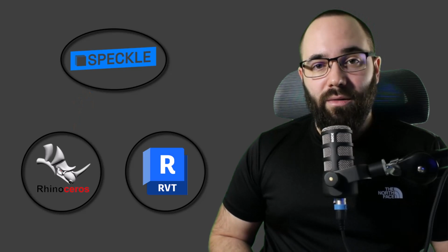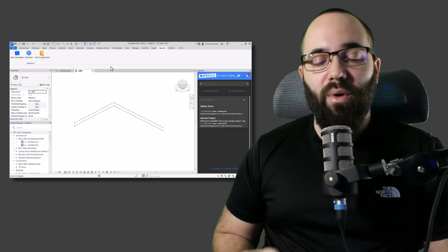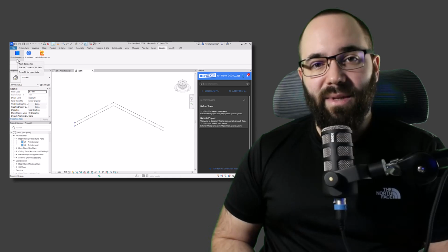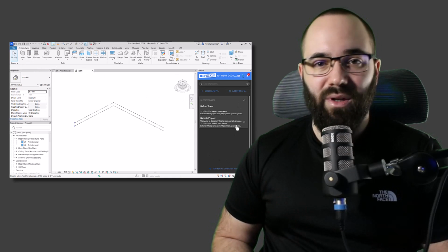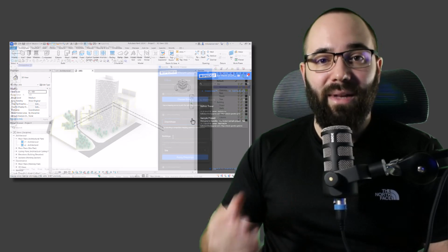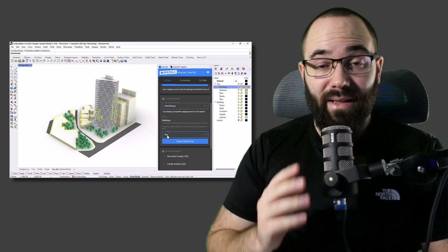So what we then do is we take our Revit project and then we pull all of our project data from that Revit file. So what does that mean? That means you're pulling all of your floor types, all of your wall types, all of your columns, families, so everything that you need, the main project information, you're pulling from Revit into Speckle.